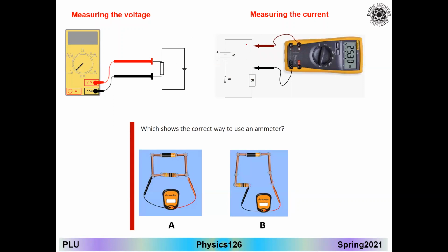When you measure the current, we need to disconnect your circuit to measure the current through any part of your circuit. So in this case, my current goes this way here. I make a disconnection here to hook up my digital multimeter, and the output connected. So basically the circuit is connected through your multimeter. And here we read the measurement in this branch, which is basically the current through the circuit or through the resistor.